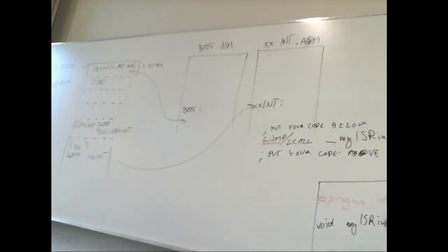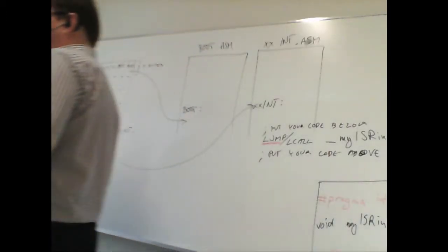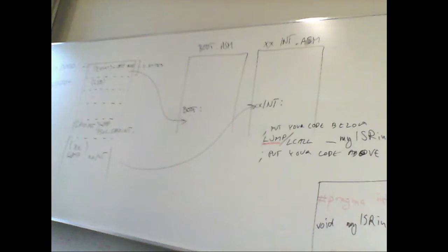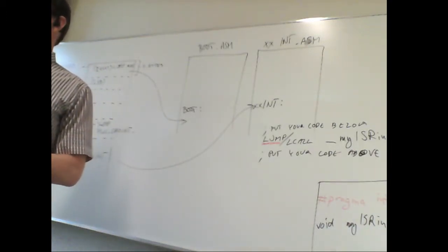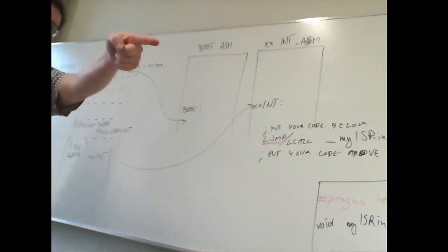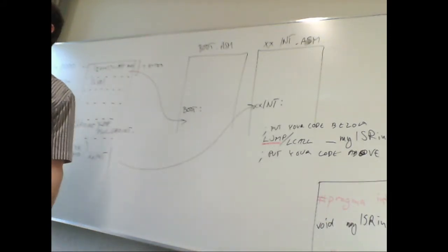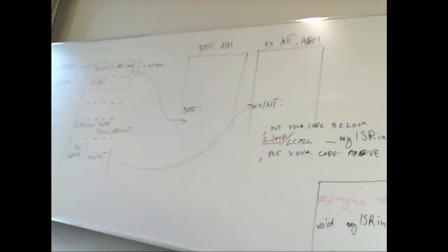If you mix those, so make a long call to this kind of function, you will get a stack overflow in just tens of instructions. Just about 20 interrupts and you are done. Yep. Well, then how about standing up? Good exercise. Okay, so this is the interrupt mechanism.